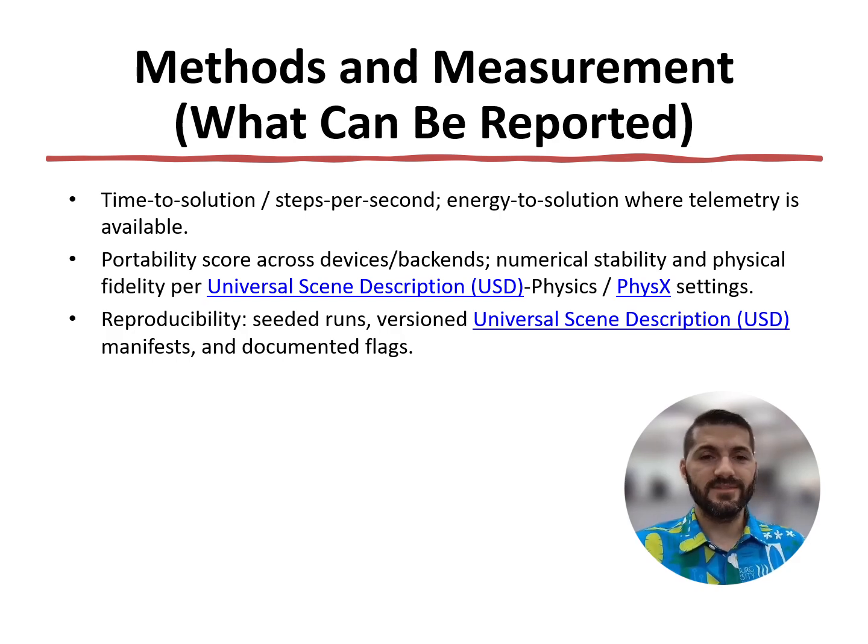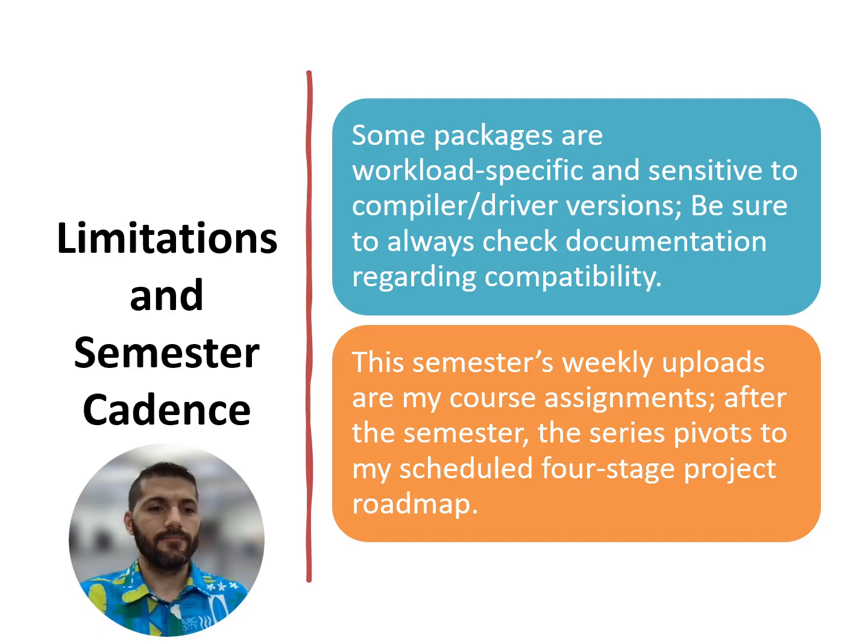And how stable is it when I'm running physics simulations and things like that? And hey, can I reproduce it? If I run the same physics simulation twice, is it going to do the same thing? Well, there's a whole seeded run for that, so I can test that within USD. And obviously, when I'm testing things across GPUs, testing compatibility, some things are going to be workload specific and sensitive to various driver versions. So if anyone is following my work or doing similar things, make sure you check that. Check the documentation because it might not work with a different driver or GPU, etc.